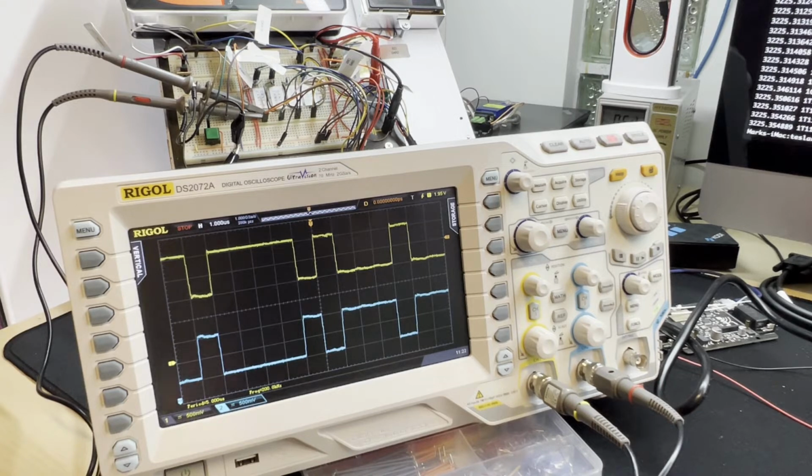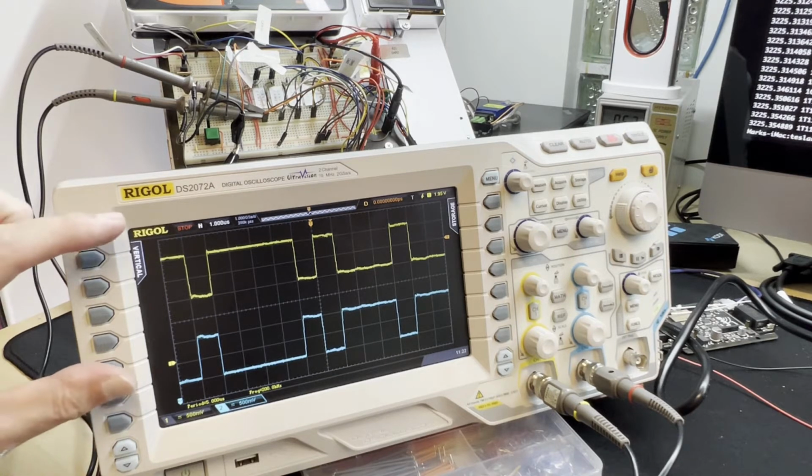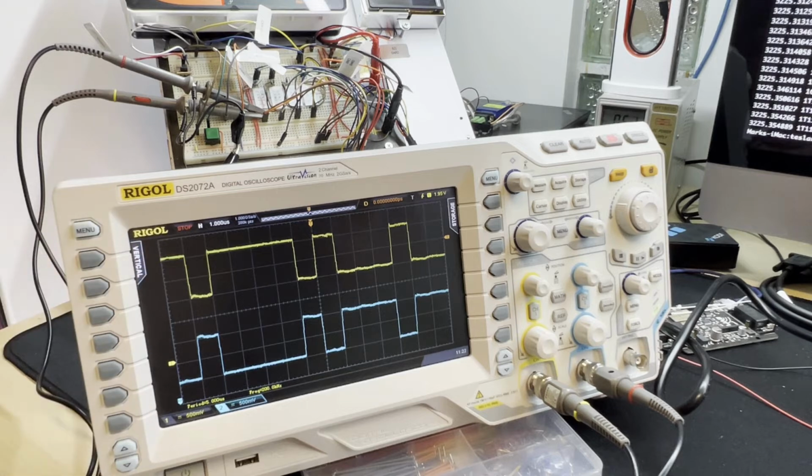Each CAN bus should be terminated with resistors at each end of the bus. This helps to minimize reflection of signals and allows for high data rates and reliable communications. In very short buses, such as our test bench setup, this is not so important, but correct termination is essential with longer wire runs in electrically noisy environments such as vehicles.